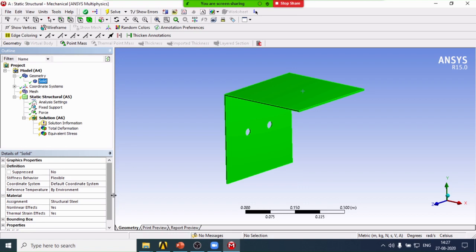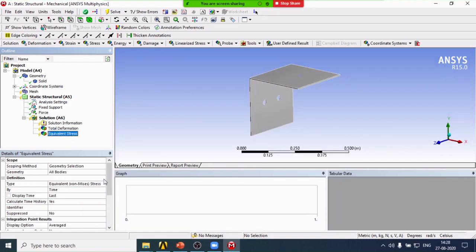Another one, you now want to get the maximum deformation. So here in the maximum results I want it. Then the same I want to do for the equivalent stress also. Then you can tell it to solve. Each and everything is ready now. Meanwhile you can answer, or you can put your questions on the chat. No one is giving an answer, I think.